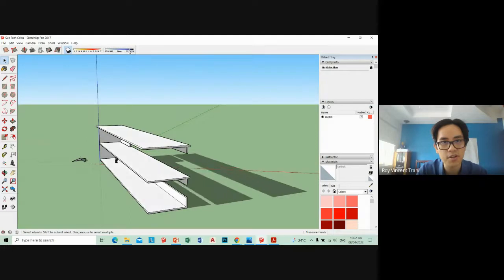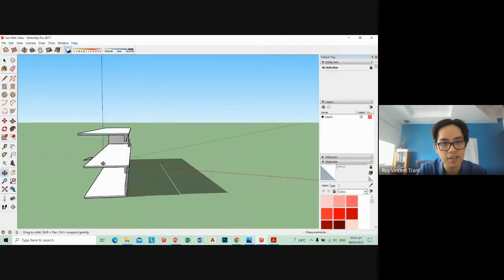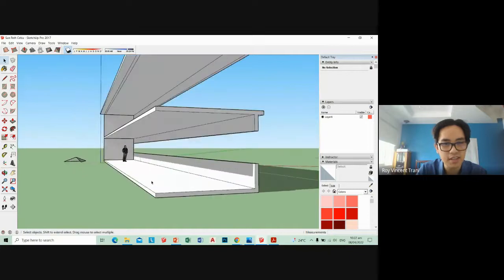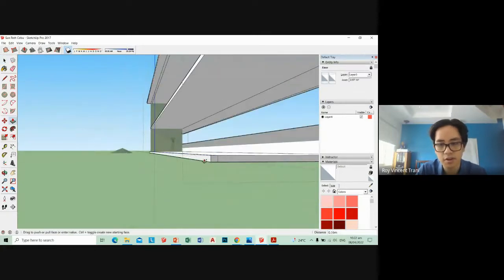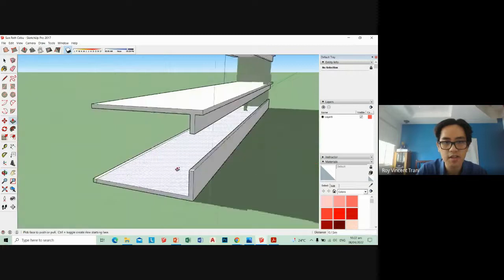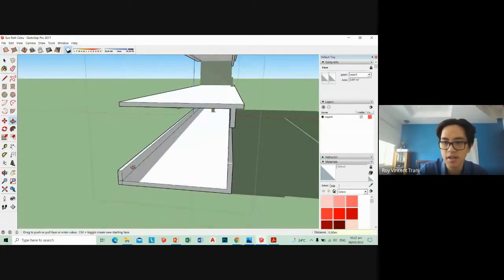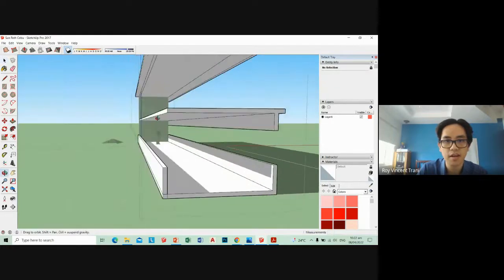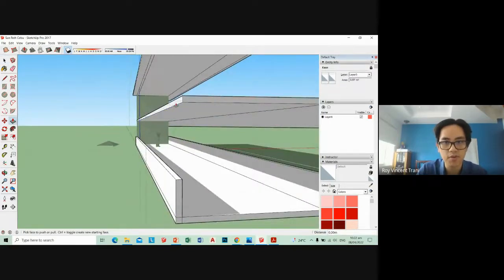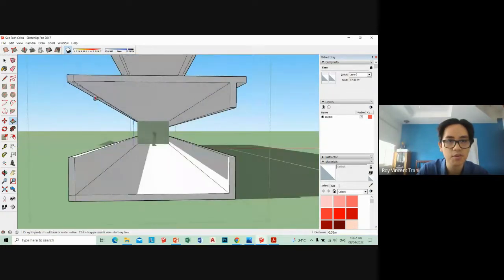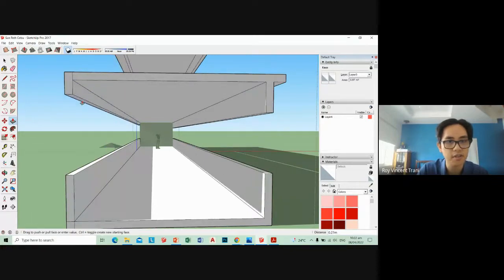And then let's look at December afternoon. Oh, it's because I don't have anything on this side. Let me copy paste this here. Let's see, a 0.15 wall with a 0.8 elevation and an extrusion of 0.9, sorry. Then let's copy this here again, 0.6 extrusion, 0.15 wall, with a 0.6 extrusion, meaning our windows are 1.2 meters in height. There we go, 0.6.